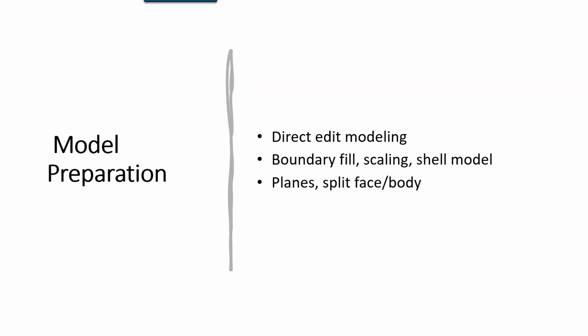Now, this isn't the full breadth of what Fusion 360 can do in terms of model preparation, right? These are just some of the most common ones that I'm familiar with, that I use day in, day out. And in talking to Mark, these are also some of the more familiar options that he tends to use to prepare his models. Right, so you have direct edit modeling, you have boundary fill, scaling, shell model, using planes to do a split face or split body operation. That's a pretty common technique to use.